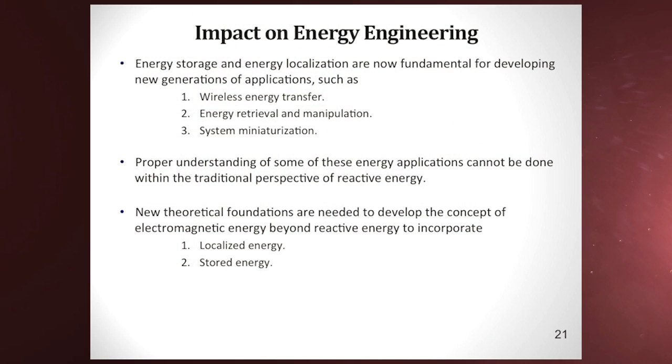MIMO systems, and I'll give an example of how these developments are used in a MIMO system to achieve certain requirements. Energy: there are many questions being raised about energy. Where is the energy in the system, and what is the definition of reactive energy and stored energy? There are actually some contradictions if anybody does fundamental research on the question of energy in the electric fields and so on. The new formulation that we have comes to a concept called localized energy and stored energy. Depending on the type of the antenna, the energy around the antenna could be localized in certain directions.